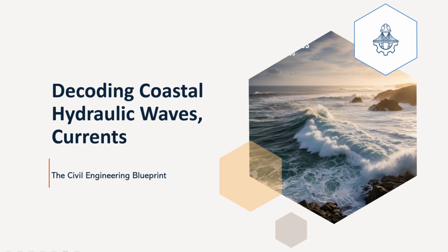So that's how much energy a wave contains per unit area. But then there's energy transfer, often called energy flux, or simply wave power. This describes the rate at which that wave energy is transferred forward, moving through a vertical plane of unit width that's perpendicular to the wave propagation direction. This is a measure of how quickly that energy is actually moving towards the shore or a structure.